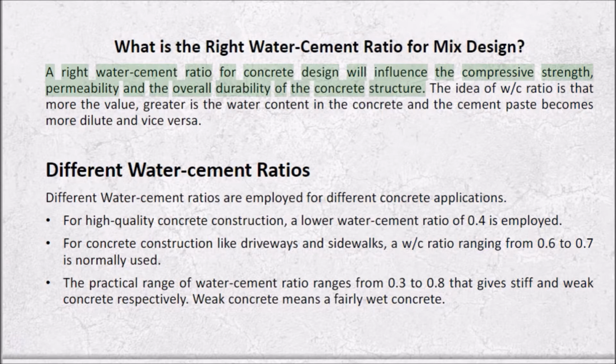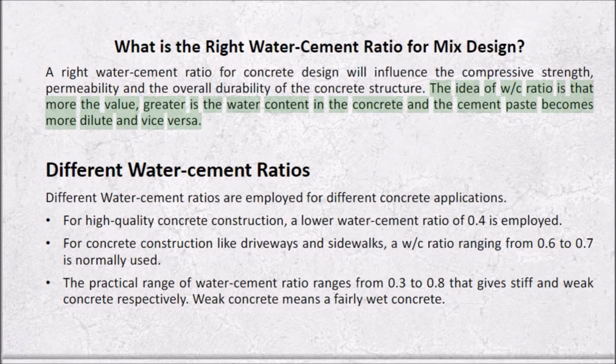A right water-cement ratio for concrete design will influence the compressive strength, permeability, and the overall durability of the concrete structure. The idea of WC ratio is that the more the value, the greater is the water content in the concrete and the cement paste becomes more dilute, and vice versa.